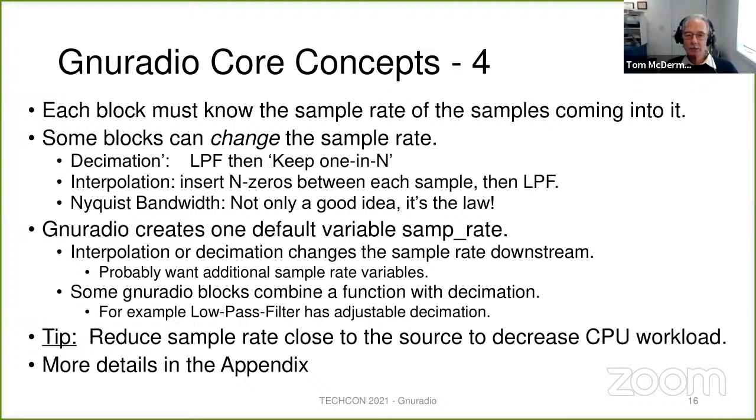Well, 1 million samples per second may make your poor computer huff and puff and work pretty hard. And it may be that you're really only interested in listening to audio. And you can't hear by ear anything higher than about 8 or 10 kilohertz. And so you may want to decimate that down to a lower sample rate. If you decimated by 10, then the output sample rate would be 100 kilosamples per second with no frequency usable above plus 50 or below minus 50 kilohertz.